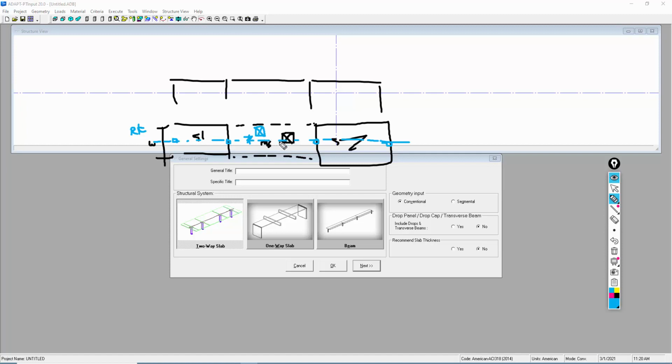of the opening. So to do something like this, what we would have to do, and I'm going to just draw this second bay here, we would actually do something where we would create something like that, where this is the width of the opening, this is the length of the opening this way, or vice versa, and this particular segment, we'll call this segment 2. Here's segment 1, segment 2, and segment 3. Segment 2 is actually bound by the reference line. So that's how we need to consider the openings.